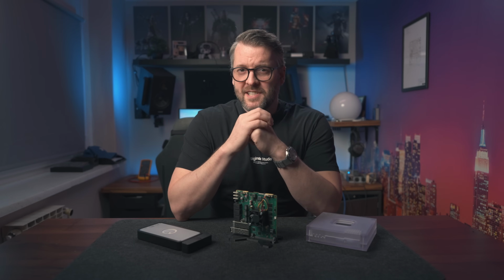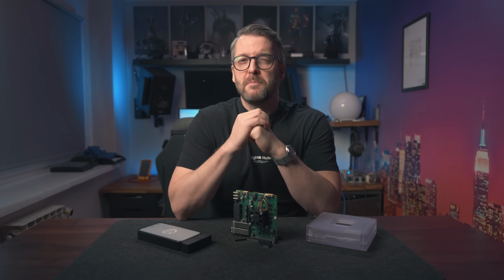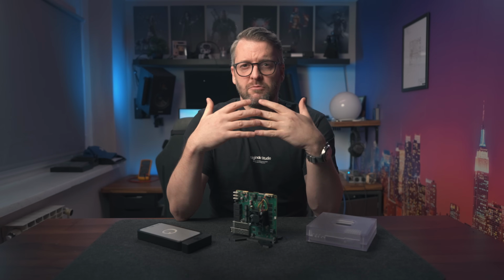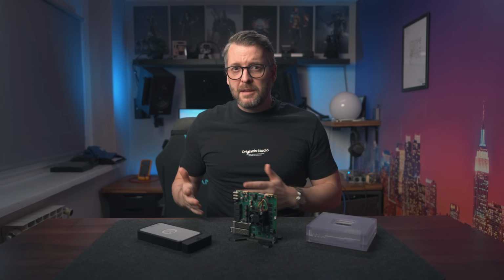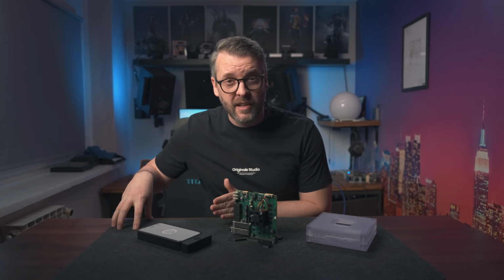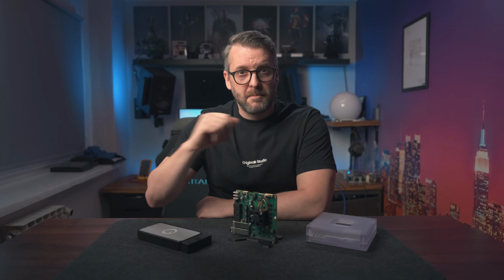Since routing all these signals can become quite a challenge, the DDR standard allows for something called bit swizzling. In a nutshell, because memory dies come in all sorts of sizes and configurations, bit swizzling basically allows hardware designers to connect bits within the same nibble to the CPU however which way they want. A nibble, in case you didn't know, is the term we use to describe a group of 4 bits. Half a byte is a nibble.